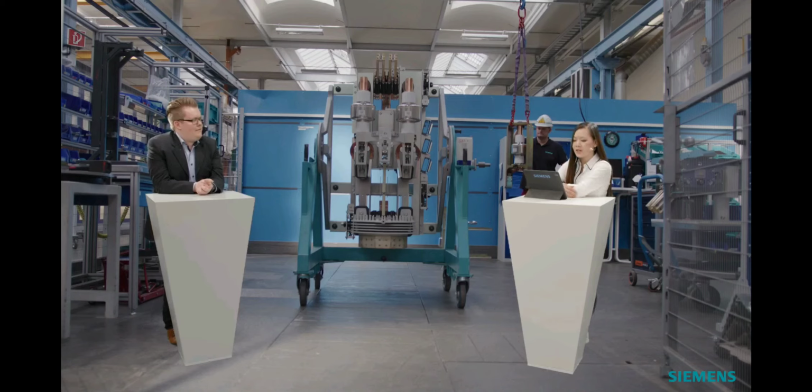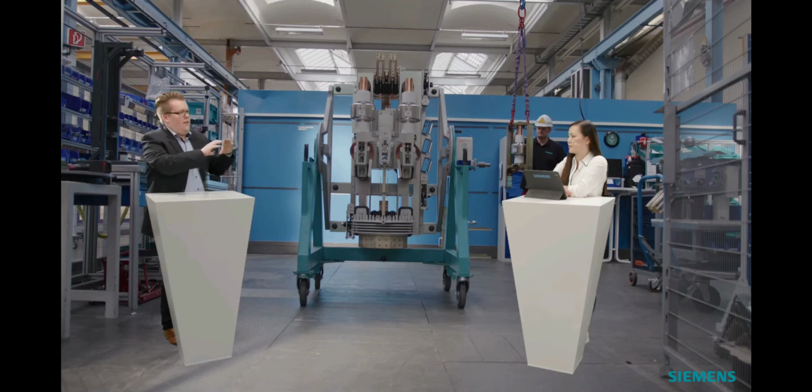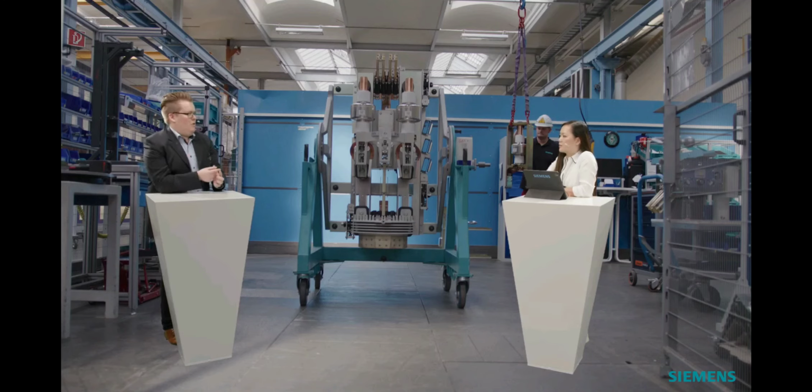The first question I got here is: are there any differences in short circuit calculation between SF6 and vacuum? Basically, for the short circuit calculation itself, there isn't any difference, because the IEC/IEEE standard applicable for generator circuit breakers does not give any difference between SF6 and vacuum. The only thing we have to consider is, of course, the mechanical opening time, for example, for vacuum and for SF6. But this is not interrupting medium specific, but only circuit breaker specific.